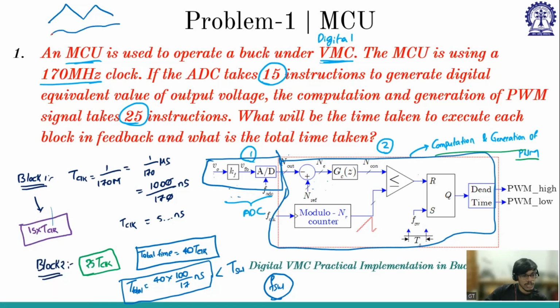So using this V0 sample, say at this point, once I get the delay, I have to give the gate pulse here, right? Whatever my controller does, it has this TSW time to give me this gate pulse information at this moment. If it takes more time, then who will give me this gate pulse information? So whatever computation the controller does should take less than TSW, which means less than a switching clock cycle to generate the gate pulse for the upcoming cycle.